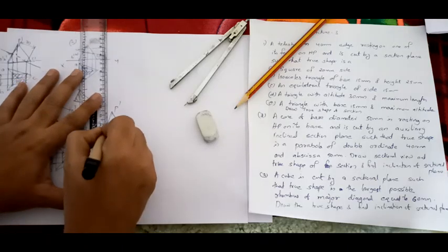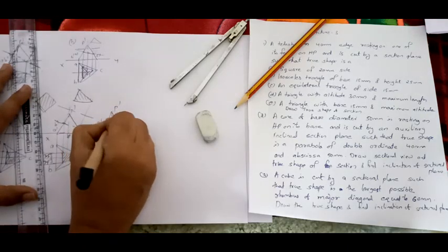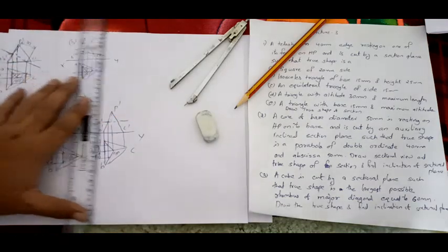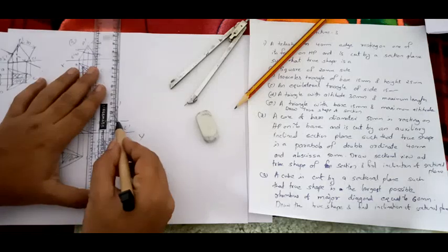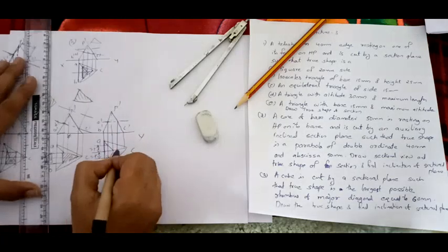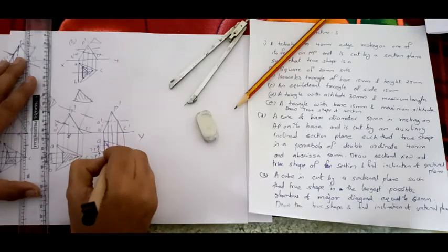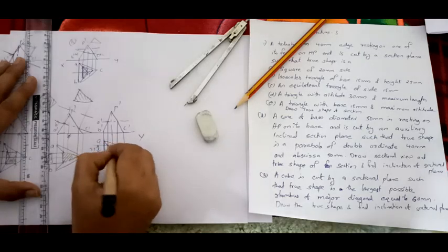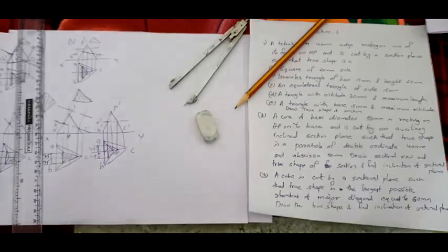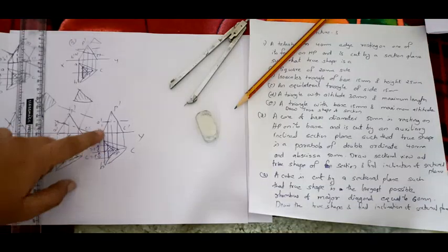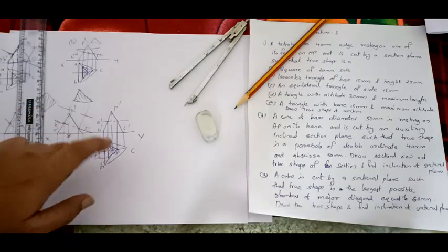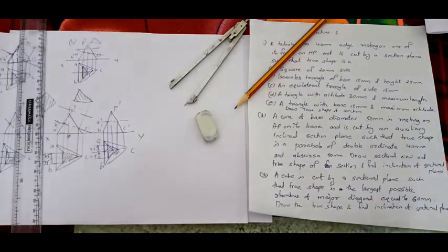Now project upwards to this face. Then draw a horizontal. So it's a horizontal plane. So draw a line. Horizontal means parallel to XY line. Now from this point cut it here. So you will get 3 points. See, this will be your equilateral triangle. So here you do not draw the true shape, right? Why? Horizontal means the true shape is already here. You need not draw another true shape.